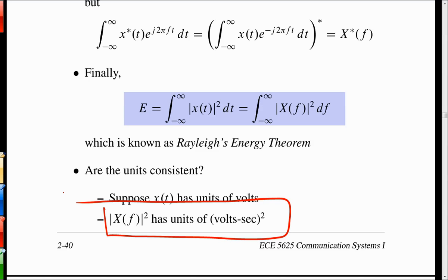So then this equation here makes sense: if I integrate the energy spectral density, which has units of joules per hertz, in frequency, I'm going to get joules. A density is usually some quantity, like a material has a certain density per cubic centimeter, and then you multiply by the volume, and you've got the mass of something. Here it's the density in the spectral density. So that works out.